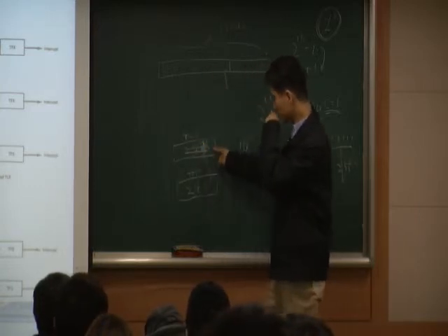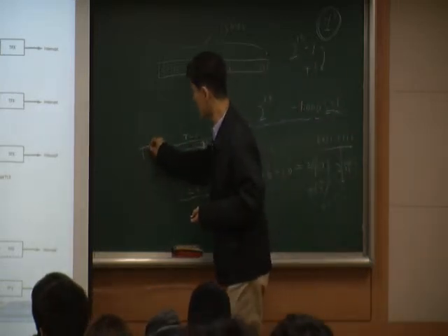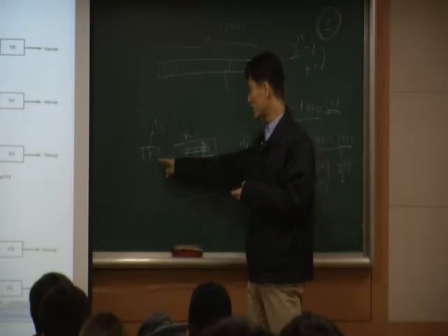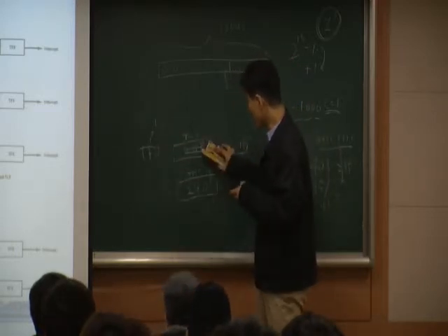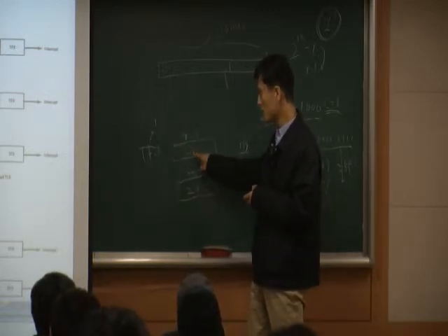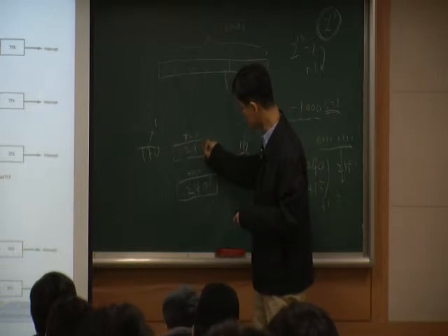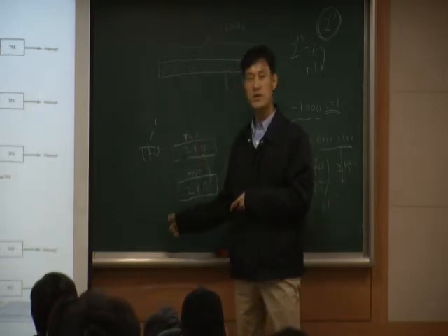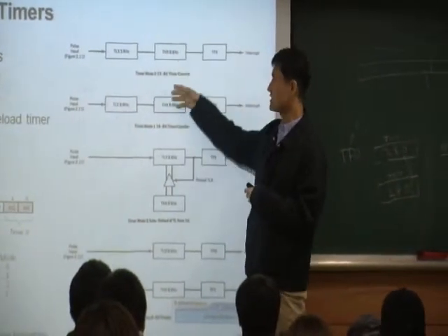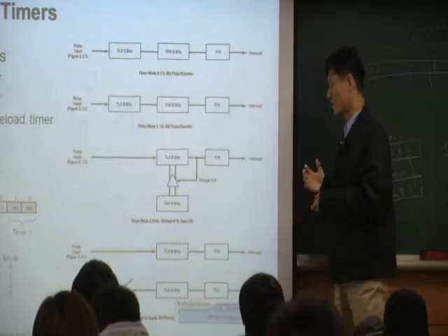And then whenever this counter becomes all 0 and the timer overflow becomes 1, that's the time the value here becomes 0. Whenever this one becomes 1, this one becomes 0. Then the hardware automatically copies this value back here and does it again. That's why we call this auto reload. This is a very nice thing, right? It's auto reload. In the other case, it's not; you have to program it every time. But this one is done automatically.